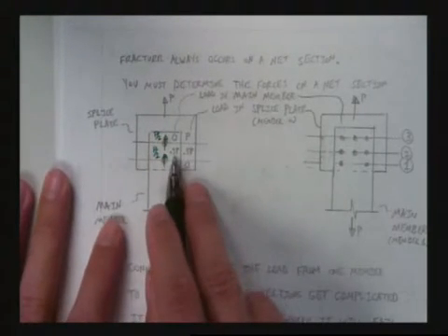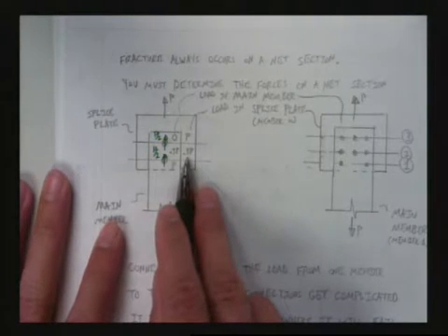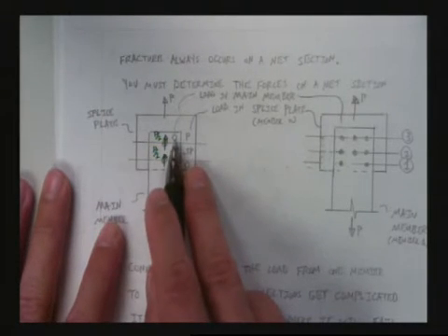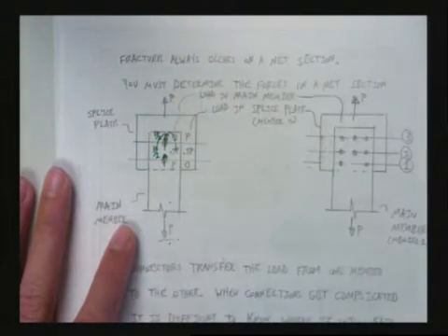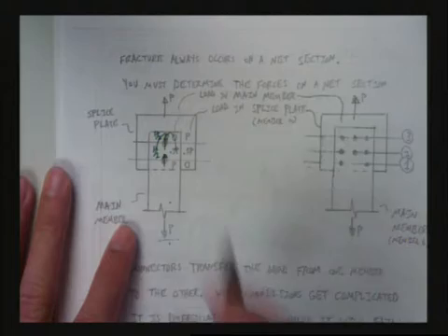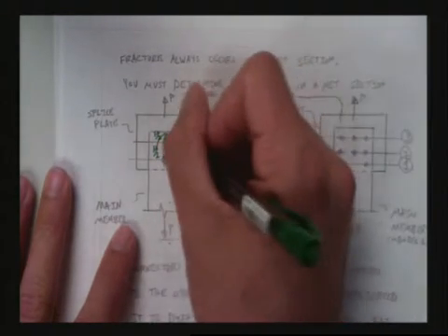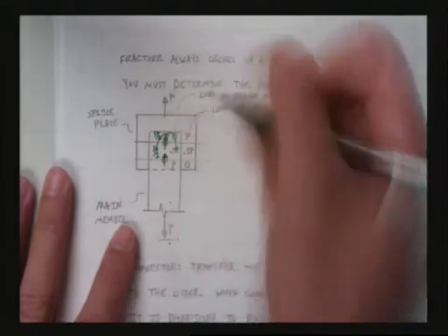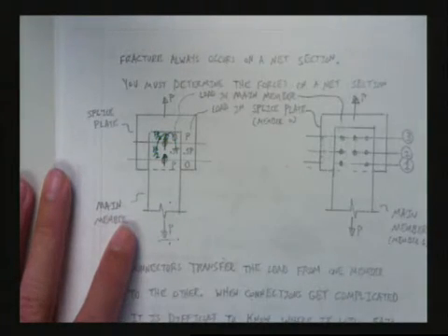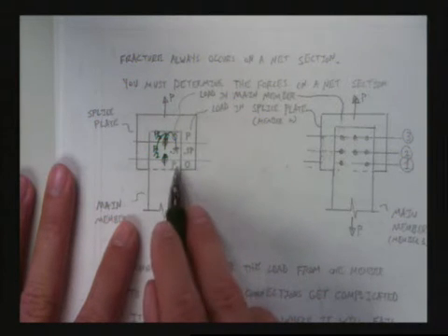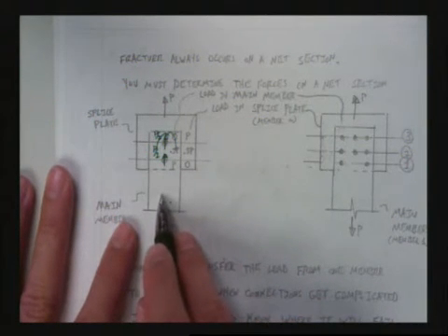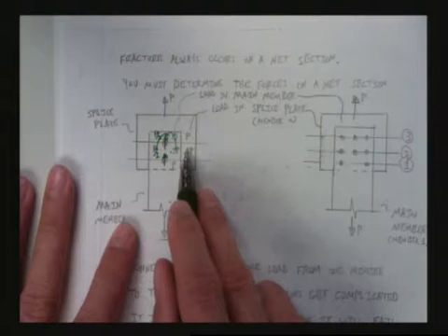So if we have 0.5P here, what do we have to have here? 0.5P, right? And now I'm telling you down here that the load, the stress, is 0. Well, that's not exactly right, because some of that stress has to turn the corner, so the stress isn't exactly 0. But if I move far away from this point, then it's about 0. You with me? It's idealized, but it's good enough for these calculations. So we can see our load is slowly going out of this plate and into this plate.